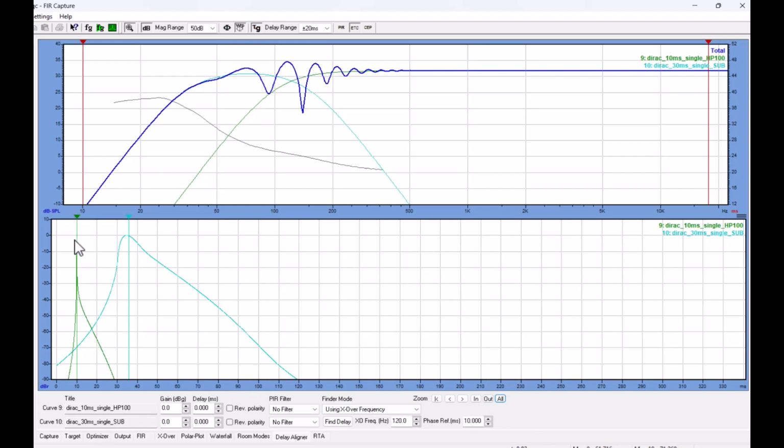And here we go to change the delay for the top and align it so it corresponds to the energy peak of each band. And you see the result here that it's not optimum, and the group delay curves are far away from each other.